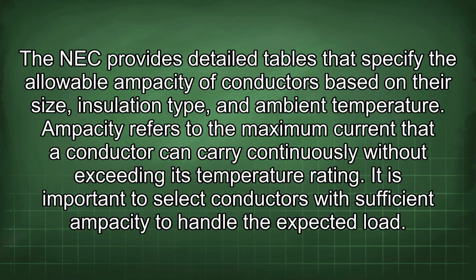The NEC provides detailed tables that specify the allowable ampacity of conductors based on their size, insulation type, and ambient temperature. Ampacity refers to the maximum current that a conductor can carry continuously without exceeding its temperature rating. It is important to select conductors with sufficient ampacity to handle the expected load.